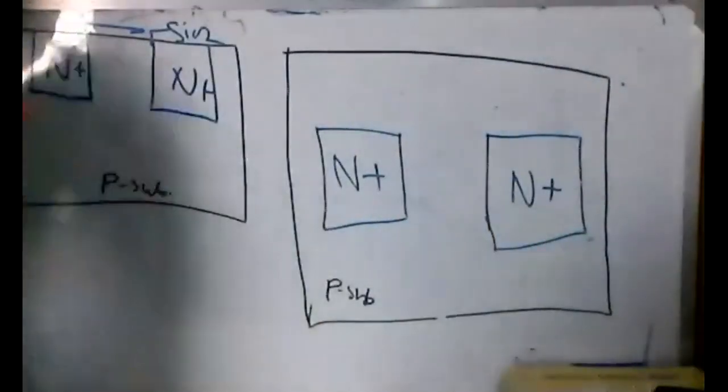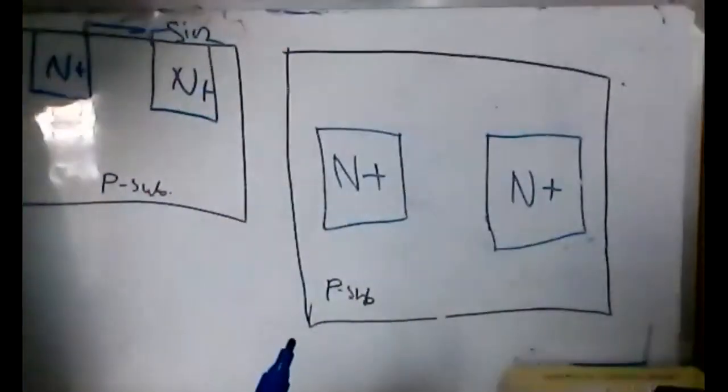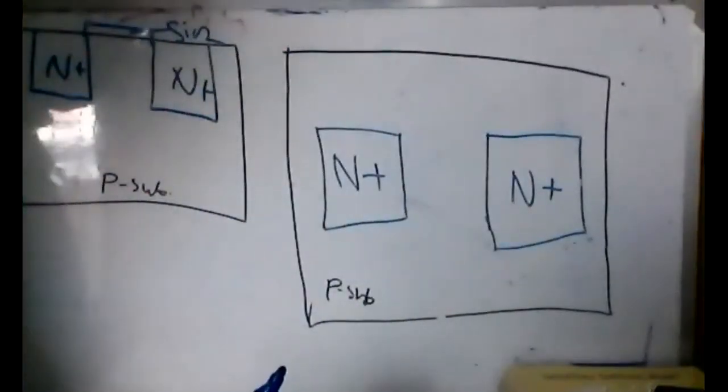Let's say this is a piece of substrate, right? And in here you make a hole, and in here you make another hole and put arsenic in here and here, and then those two areas will be n type. N plus, because it has more concentration of electrons, so it will turn into N plus type. And so this will be considered as a source and drain.